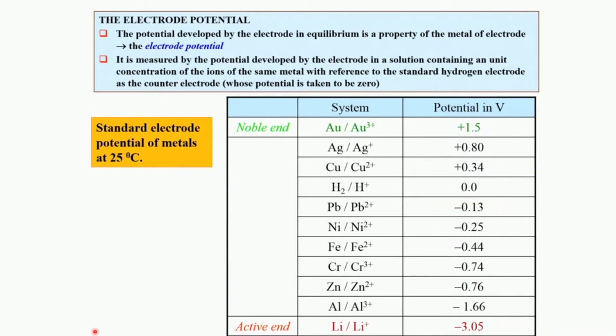Now, if you quickly go through the tendency of the different metallic materials to corrode, you will find that they vary a lot. It depends on the typical free energy change associated with the process of corrosion. As I mentioned, the metallic state is the unstable state. So, whenever it corrodes naturally, there is a decrease in free energy. This particular free energy change is usually negative. So, the negative Gibbs free energy change is basically the driving force for corrosion.